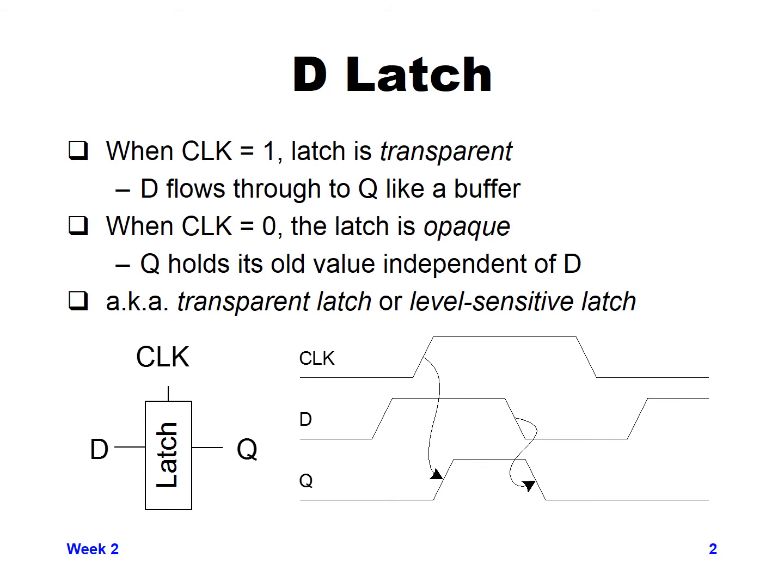As soon as clock goes high, it causes the latch to become transparent, and so the output will follow whatever D is. As soon as clock is 1, the output Q is dependent on the value of D. Since D is 1, the output of Q will go from 0 to 1.